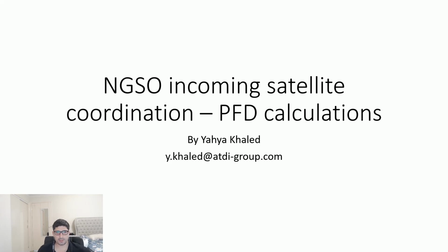Hello everyone. So the topic for today is non-geostationary orbit satellite coordination using HTZ Communications or HTZ Warfare. The idea is that we want to import from ITU the notice for coordination from a specific authority or government, and we're going to import these satellite coordinates into the database and then calculate the PFD and establish if it is exceeding the criteria or the threshold over a specific country.